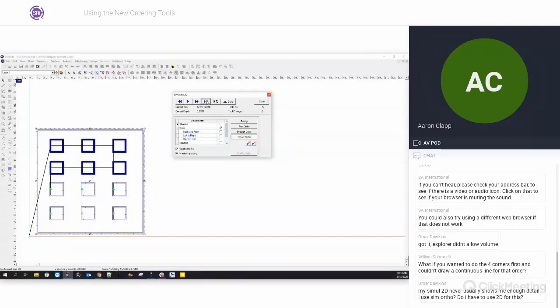And now as I can preview here, it's going to go in the exact order that I told it to, even though they're grouped together. So this is something that was always kind of an issue in EnRoute in the past, but this order by group is going to help fix some of those issues. Also, just to be aware, this box here does need to be checked. If you uncheck this box, it does eliminate that. In the past, EnRoute did do a maintain grouping, but you were never able to organize the pieces inside the group.